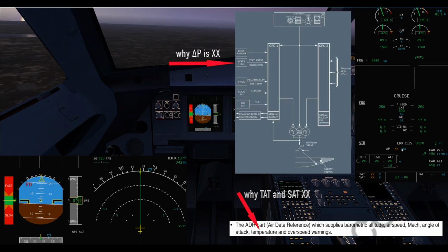As you can see from the cruise page, the total air temperature and static air temperature are not valid, because the cabin pressurization computers need information from ADIRS, and this information is lost.